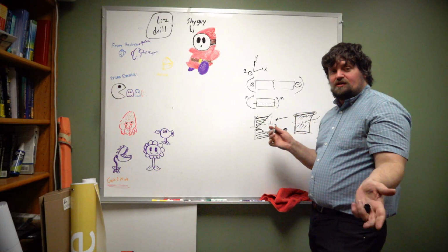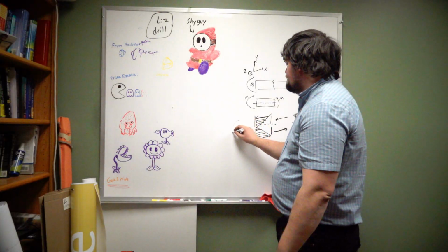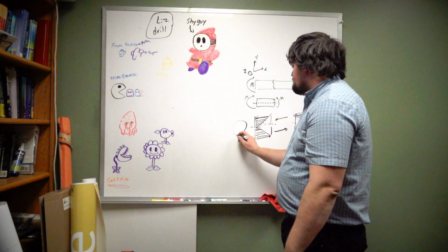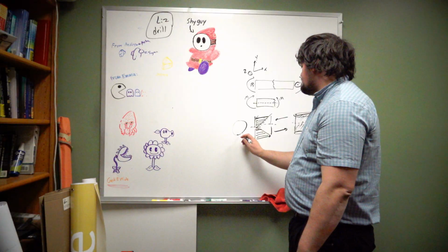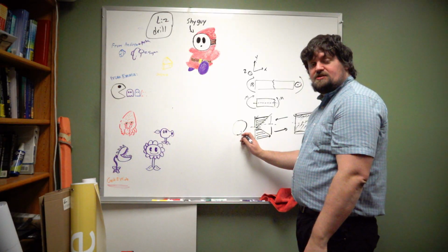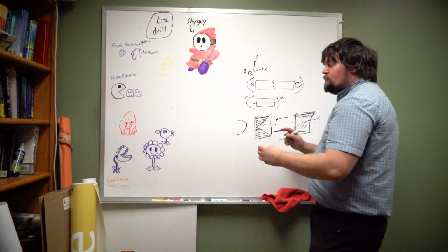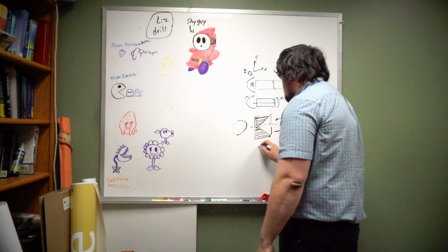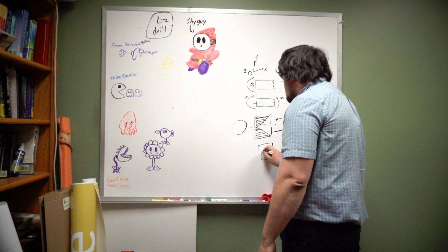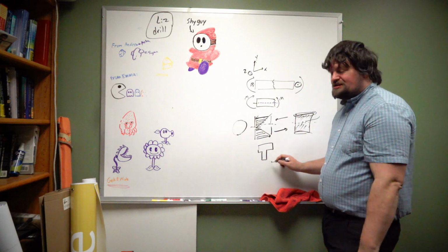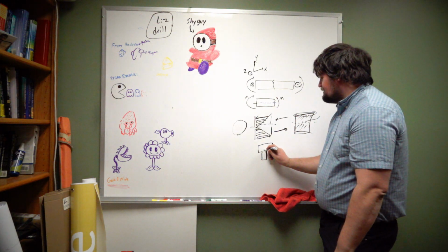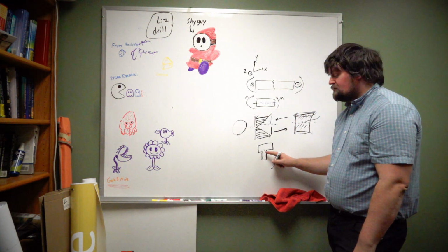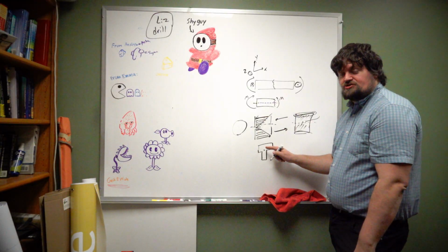Okay, and that would work well if it's a rectangular beam. If it's a circular beam, same thing applies. Your maximum compression is going to be at the top, and the maximum tension is going to be at the bottom. Okay, but we can look at another shape. We can go ahead and look at a T shape on this. Now if you look at a T shape, the centroid on here is not actually in the center. It's closer to the middle of this larger beam.